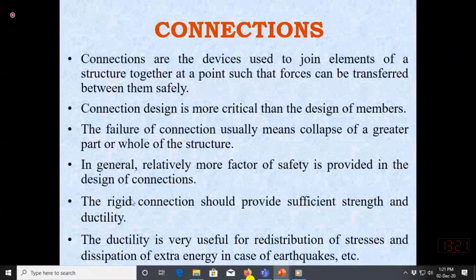Actually, when a rigid support yields, the behavior of the support changes from rigid to shear connection or simple connection. We have not discussed this topic at the moment, but I will explain this phenomenon of stress redistribution in our beam topic.